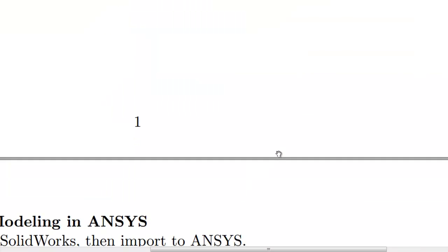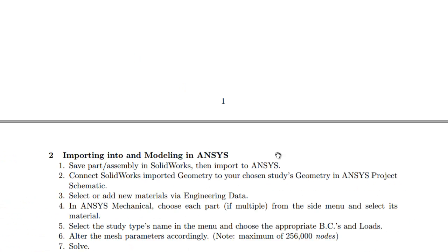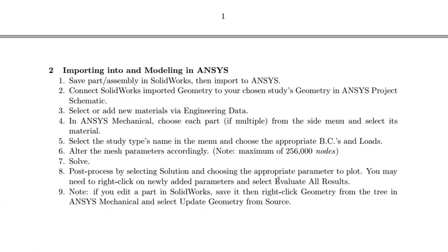Also, here at the bottom, it'll summarize what we're going to do. I'll zoom out here. It's going to summarize what we do to import into ANSYS. So we're going to go through all this process here. The biggest thing to note as we do this is the kicker here. At least the license that I'll be using, which is the introductory teaching license, so CFD Mechanical teaching license, we're restricted to 256 nodes. Now we're not going to go anywhere close to that this time. But just to note, for those of you using an educational piece of software, you're restricted there.